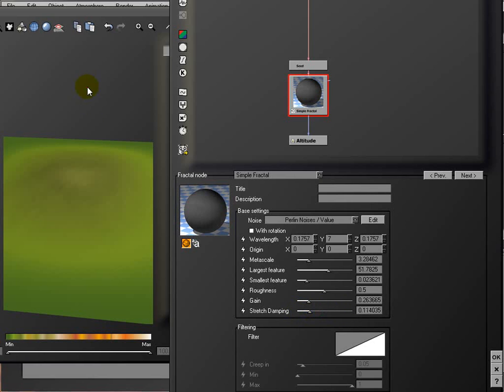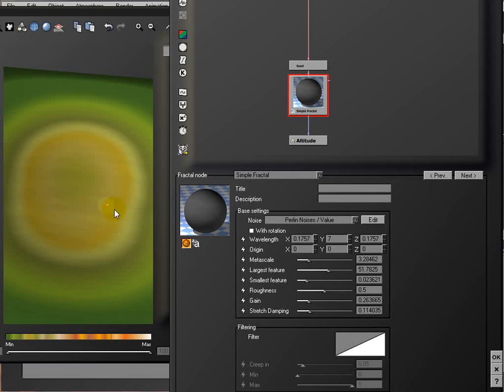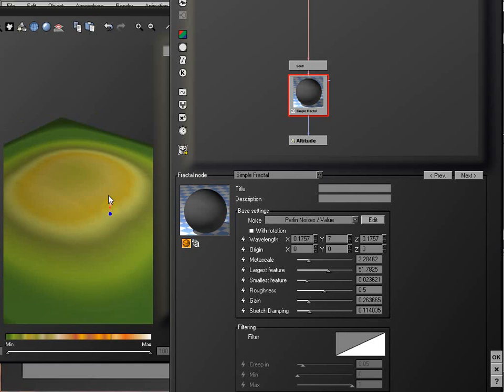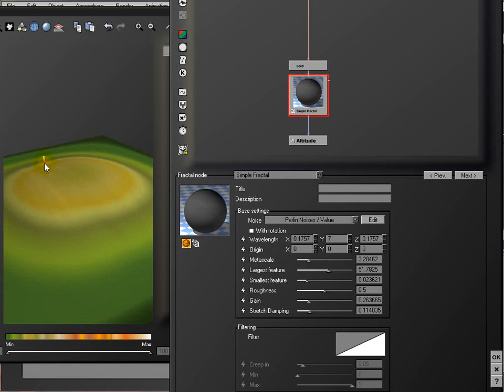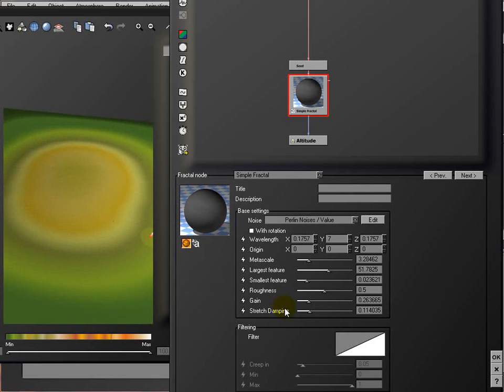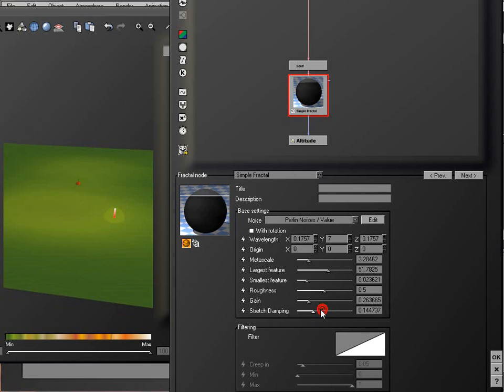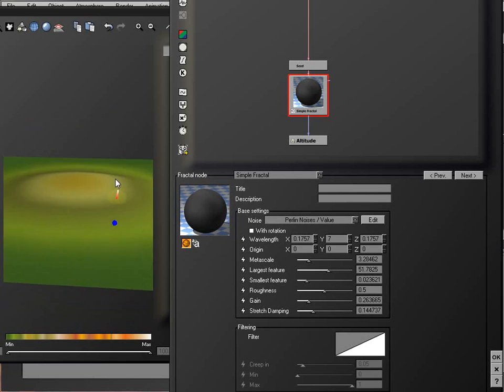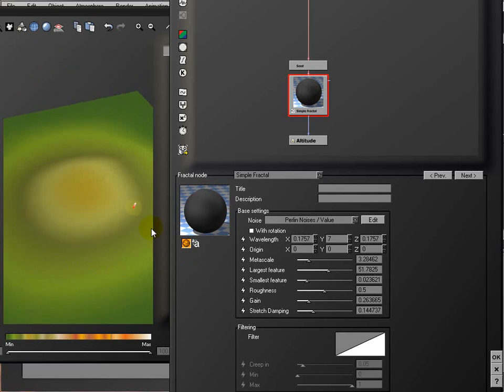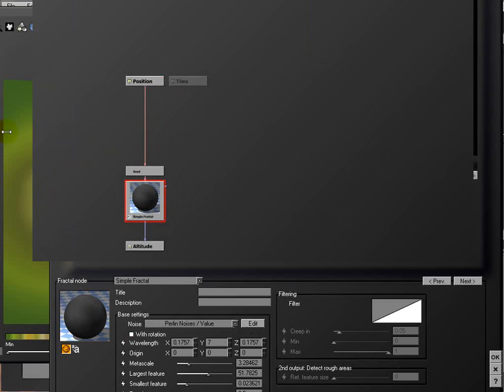So in some cases, I was using it to create maybe some kind of sliding effect on hills, or if you want to create a snow look and this kind of wind erosion, you probably won't work with this stretching much, just slightly affecting it. So you still have some mark, but not that obvious. Overall, that's actually what it does. It helps to remove this artifact effect if you increase wavelength in a specific direction. Okay, so let me increase this one.